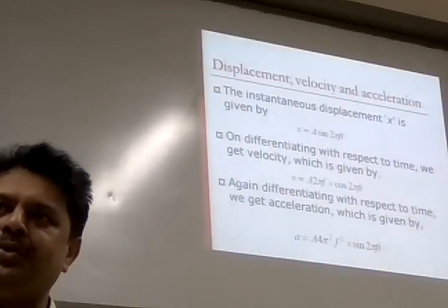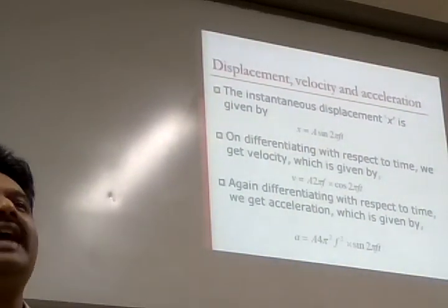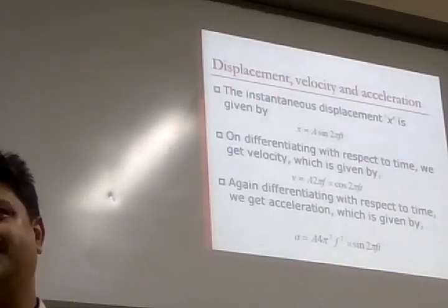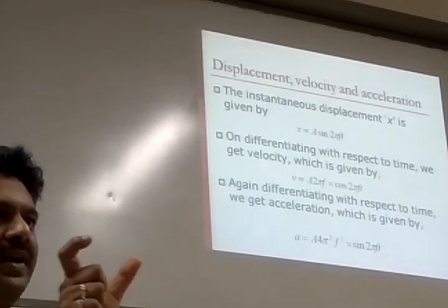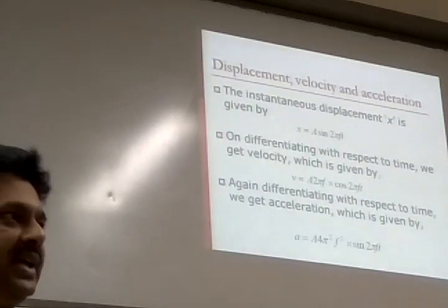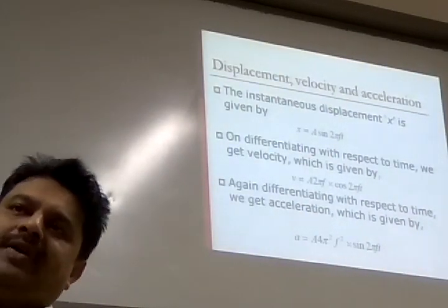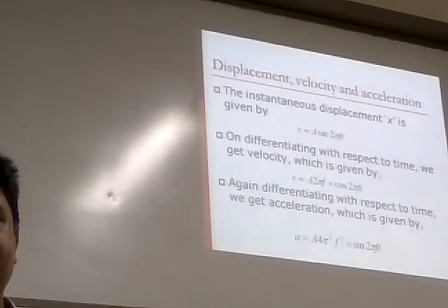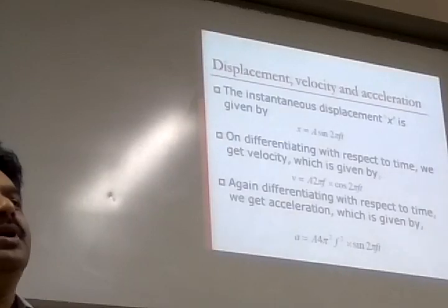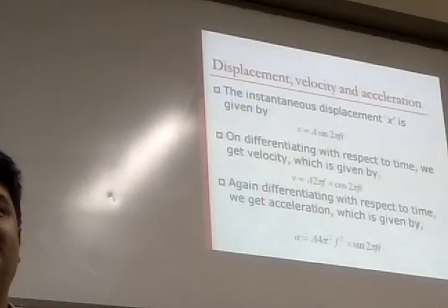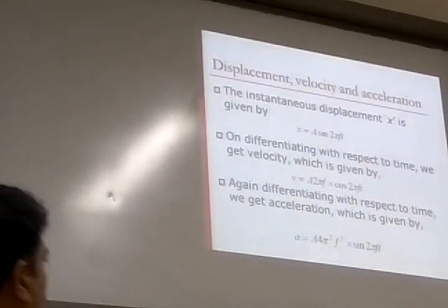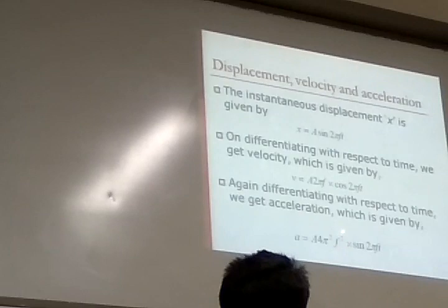And the device which is used for measuring acceleration, we call accelerometers. Acceleration is measured, that's why it's accelerometers. In your syllabus also, the keyword given for vibration measurement is accelerometers. The very reason is, if I want to measure displacement, amplitude is less, velocity is a little high, acceleration I have 40 times the amplitude. That makes my job easy to measure. So people use acceleration. Also look at one more. I draw your attention to f square. My goodness.